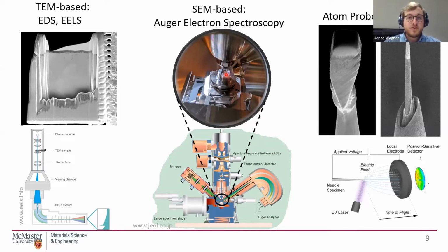It can just be put in the holder. It must be able to withstand ultra-high vacuum without outgassing. That's basically one of the few limitations. But that's it. No sample prep. Right? And here in the schematic, you can also see a second gun. It is a broad beam argon gun, which can be used for charge compensation, but more importantly for us, for elemental depth profiling by sputtering.